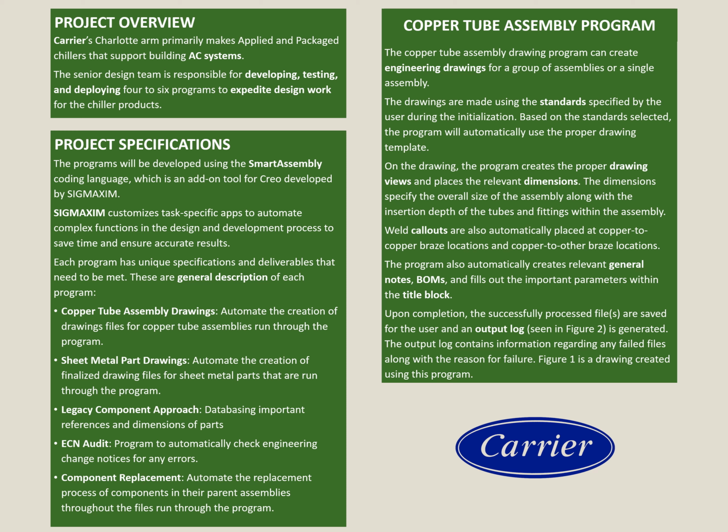Additionally, what this does is it creates the drawing views, relevant dimensions, insertion depths, weld callouts, general notes, bill of materials, along with filling out the important parameters within the title block. After the files are successfully run through the program, an output log is generated, which contains information regarding what files passed and what files may have failed, along with the reason for failure.